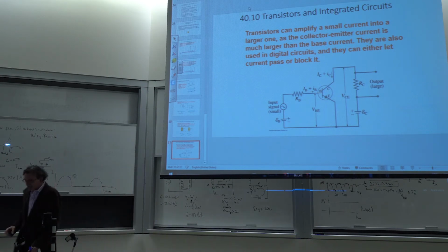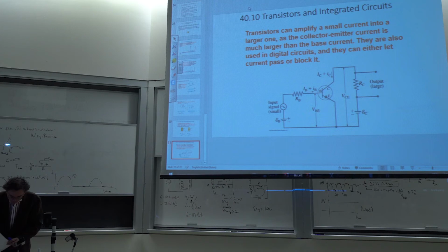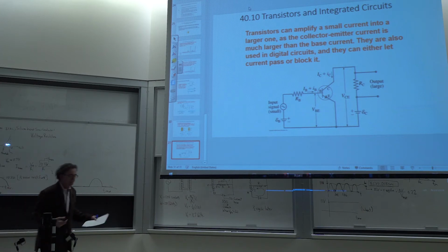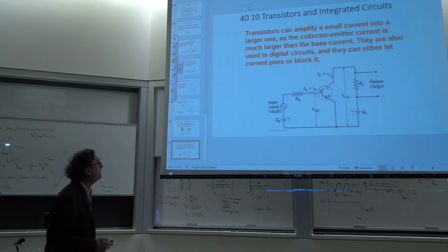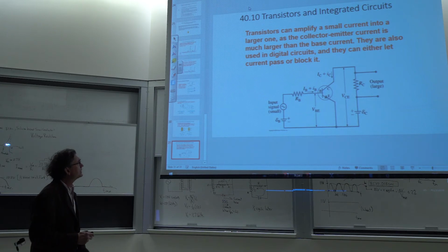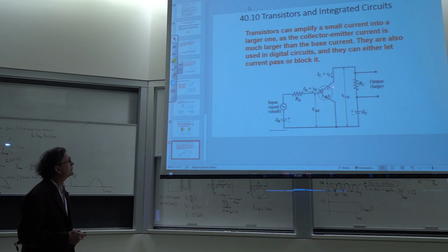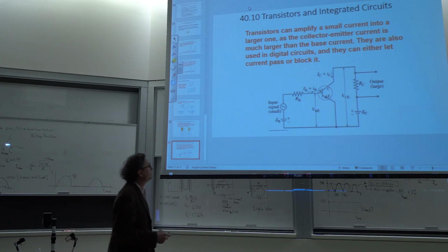So the way we approach this, and maybe the first thing is to tell you the end result of how to look at this picture globally before we get into the details, is to think of it that there are a number of components on this circuit that we should go through. First of all, there is a voltage, which we call EC, the collector voltage, which is keeping this collector up at some positive potential, usually 2 or 3 volts above ground.